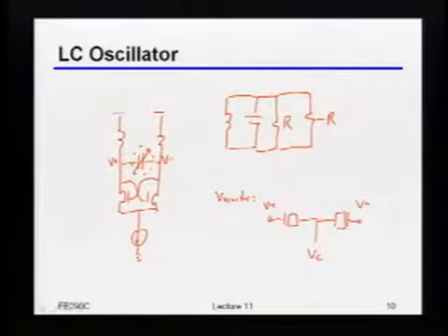Any quick questions on this one, or are people good? Okay, good. So obviously what you can do is either build a ring oscillator PLL or build an LC PLL. Just really quickly, why might you want to do one versus the other? Why might you want a ring PLL? What's nice about the ring? Area. Say that again? Small area. Yeah, it is indeed very small. It's compact. What else?